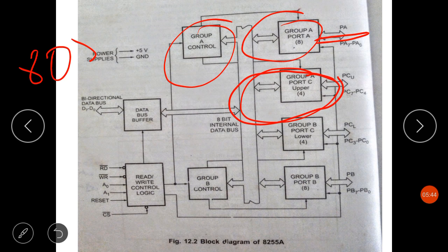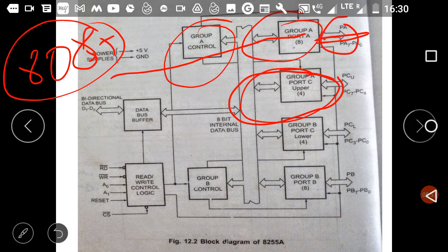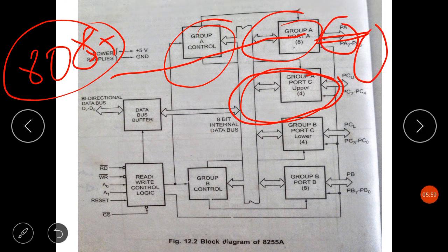For bidirectional data transfer, whatever data is sent out by the microprocessor through this port A appears on the bus connecting it to the peripheral only when the peripheral requests it. The remaining lines of port C, that is PC0 to PC2, can be used for simple input-output functions.